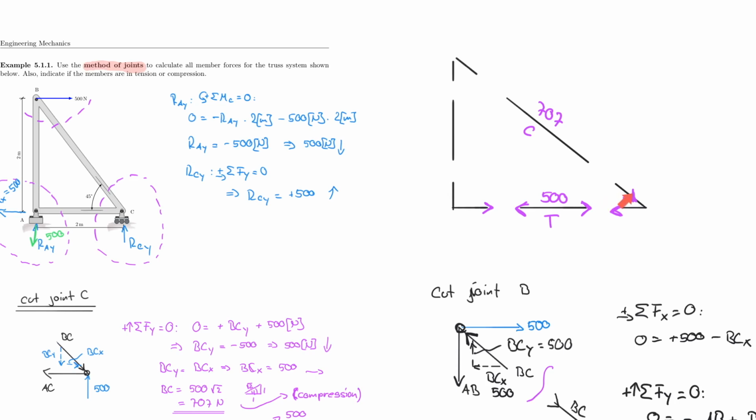Once again, here it's pushing on the node, so here I have to be pushing on the node as well, and here I have to push towards the member inside. So the way to properly show that would be as follows. It looks a little bit strange the first time you see these arrows here, but it is correct. So now they are in compression.